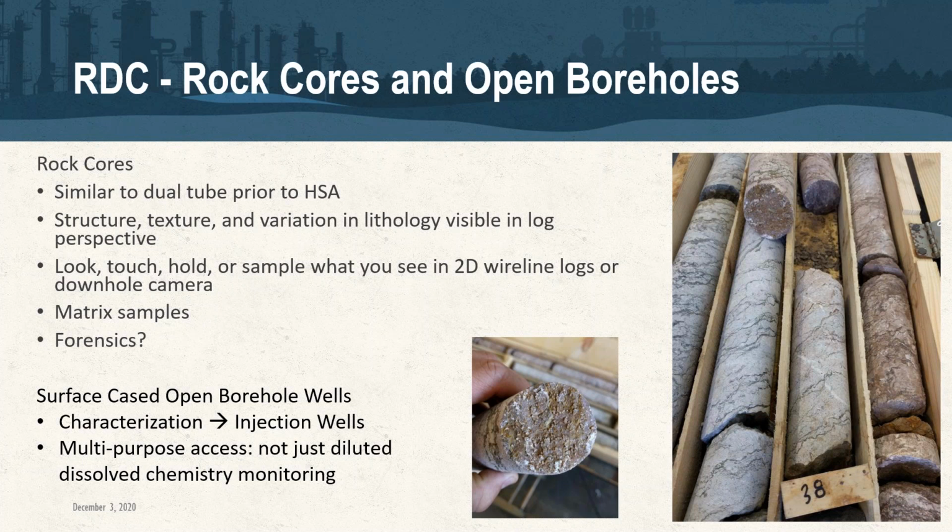And so it's quite crucial as part of any sort of remediation investigation plan to include with your geophysics some sort of coring schedule, and actually having those cores available to interrogate the borehole prior to doing any geophysics or any follow-up investigation work on those. And I like to think of this in context of looking at an overburden type scenario, running a dual tube liner down prior to advancing your hollow stem augers. Having that core, that dual tube liner in front of you allows you to look at the structure, texture, and variation of the lithology in log form, being able to look at it in front of you on the table rather than a composite blob of stuff coming out in a pile.